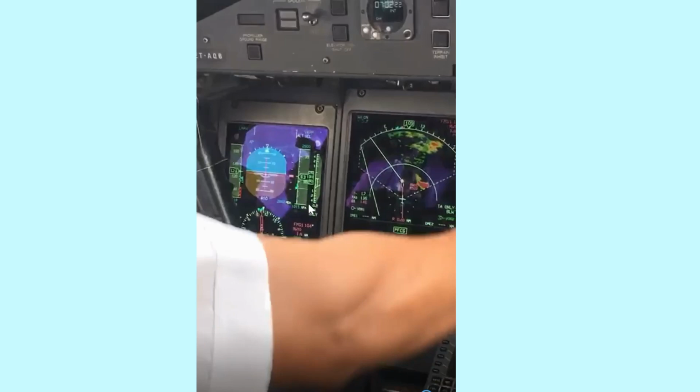Now, if you compare how you're able to see the black wing bars, which are quite big in their appearance, and you can't miss them because your eyes are straight here, compared to the small digits that you see here, you will appreciate that the black wing bars are a very good reference. So if you keep them floating between the horizon and the negative 2.5 degree line, right here where it is right now, if you keep the pitch somewhere there, you will be assured of the rate of descent to be appropriate.